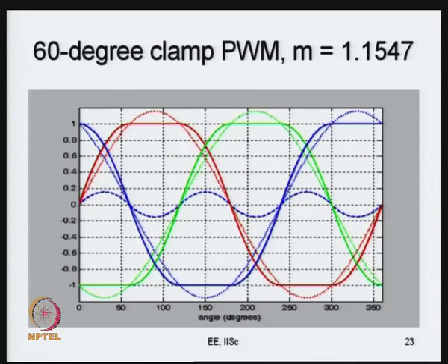The other advantage you can get is, of course, you are not switching for one third of the cycle. Therefore, the switching loss can be reduced, and for the conduction loss, you see the positive device will get heated more because of continuous conduction. The same way the bottom device in that R phase leg will conduct continuously here and will get heated up. So, they get heated to an equal extent if you look over a fundamental cycle. So, it is distributed. Again here the assumption is the line cycle is much shorter than the thermal time constant. So, it takes a long while for the heat to get distributed.